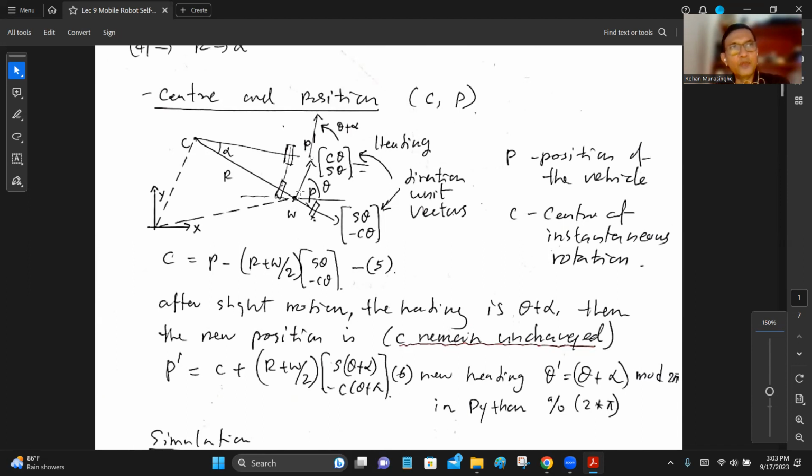If you prefer to have X along the heading and Y lateral to that, that's also fine. I have done it here because I wanted the world coordinate frame with Y vertical and X horizontal, because everybody is more comfortable working with that kind of world coordinate frame. Accordingly, I use the smallest angle as the heading theta, so that my Y naturally becomes the heading direction of the robot. Only for that reason I use that.